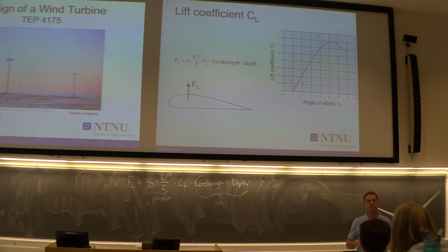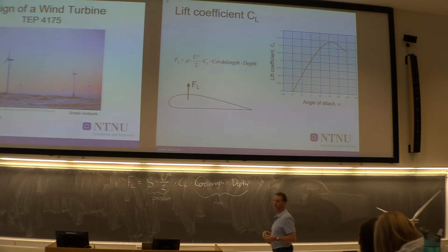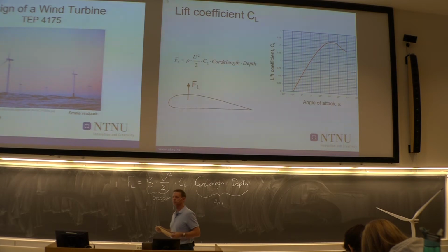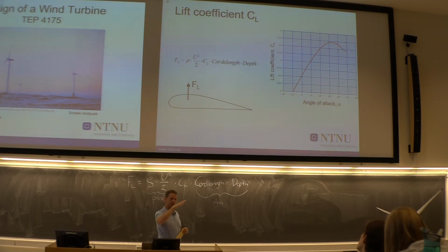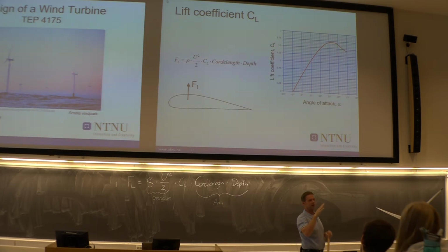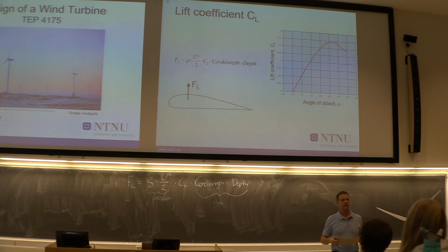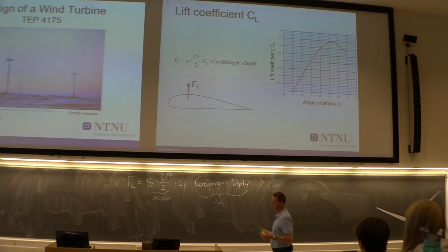degrees angle of attack. Next time you go into an airplane, take a look at the nose, on the side of the nose. There is a small wing there hanging on the side, which is movable. And that is actually telling the pilot what angle of attack he has on the airplane. At one point, that will give him a warning if the angle of attack is too high. It's called a stall warning. All airplanes have that kind of equipment.